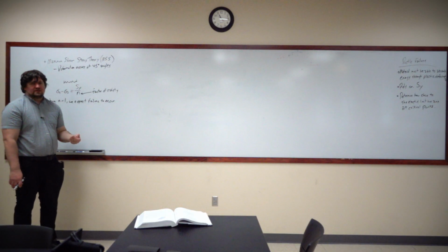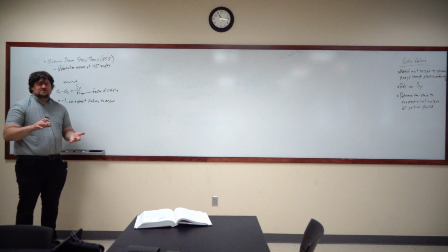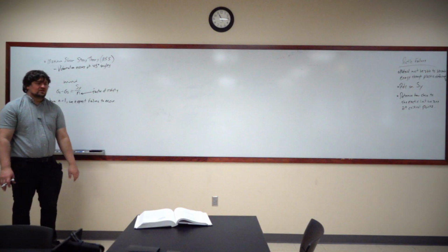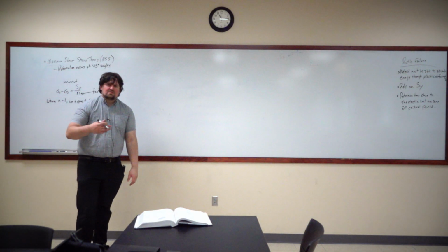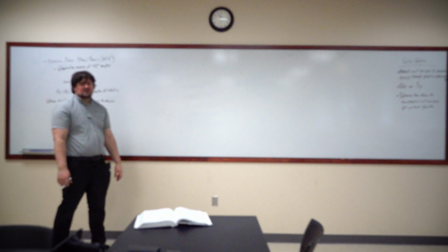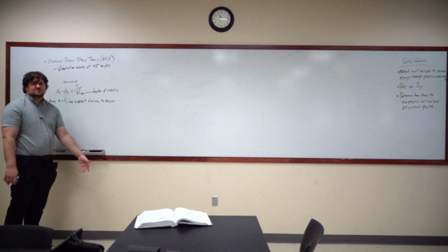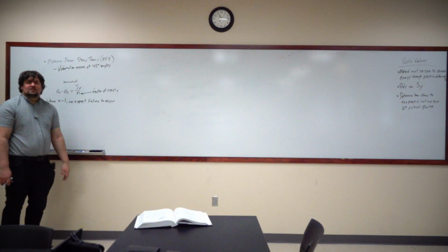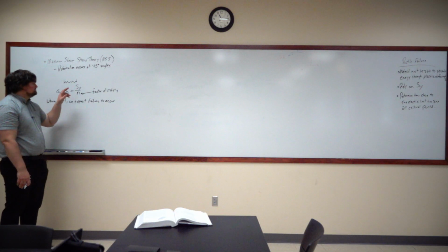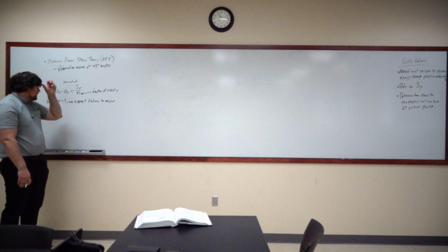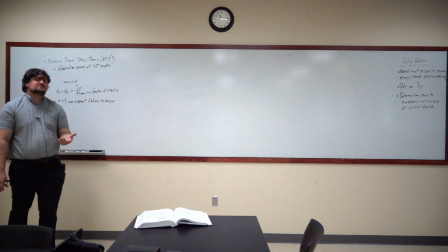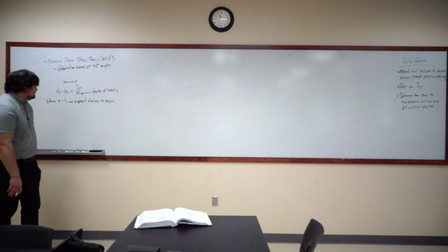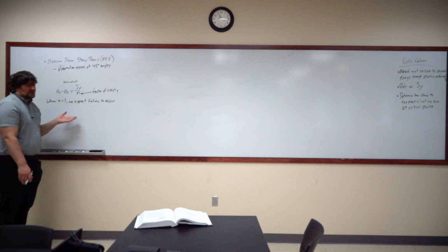So having a billet from one batch of material where you may have a whole bunch of bolts or something, we can determine what that static testing value is, and then we can apply that to the material, and then from there we can make our calculations. When n equals 1, we would probably expect more than 50% of our samples to fail. That's basically what we're saying.